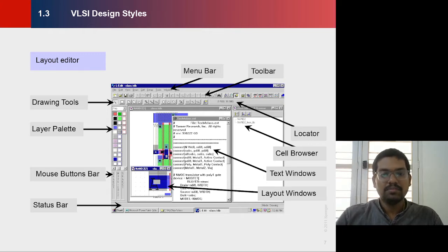For example, in the last semester you studied the VLSI design course, where we used different colors for N diffusion, P diffusion, and polysilicon. We fixed only a few colors: green, yellow. But metal is also different; we have used two metals. Depending upon the design, you can choose more metals. If we have more metals, whichever is the last will have the least resistance. If you have M1, M2, M3 up to M9, metal 9 will have the least resistance compared to metal 1 to metal 8.